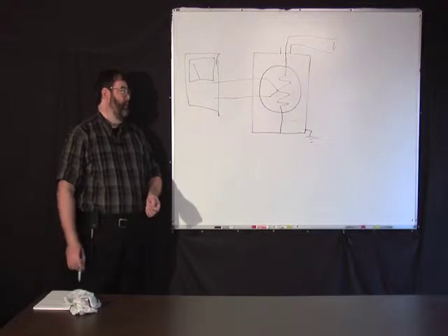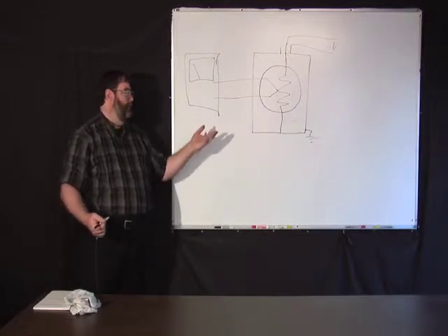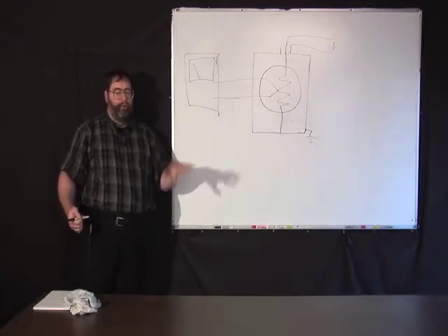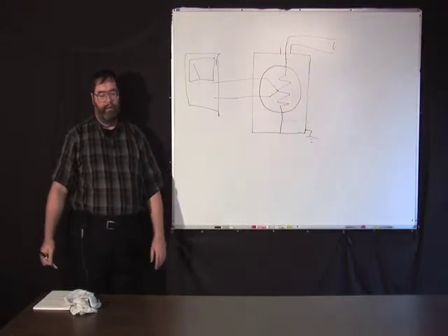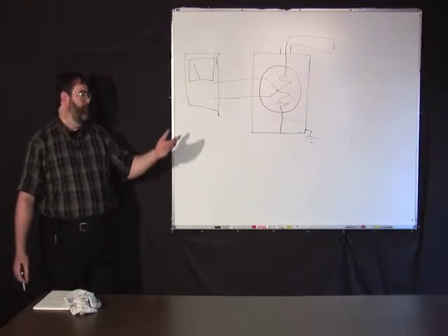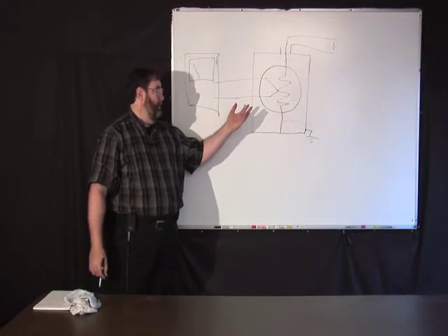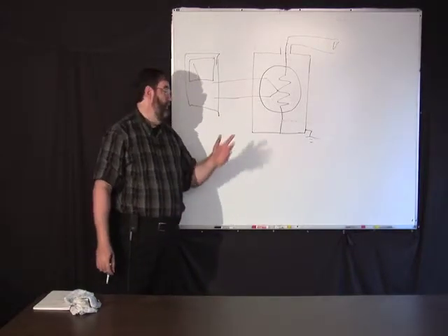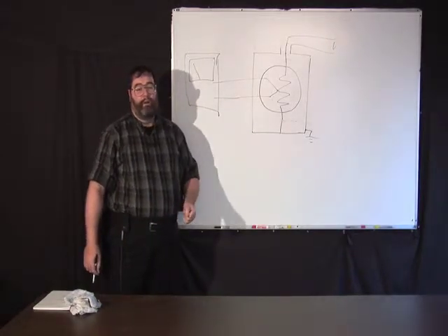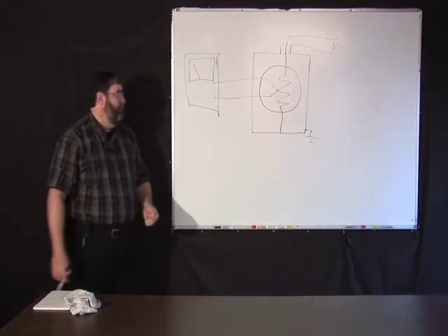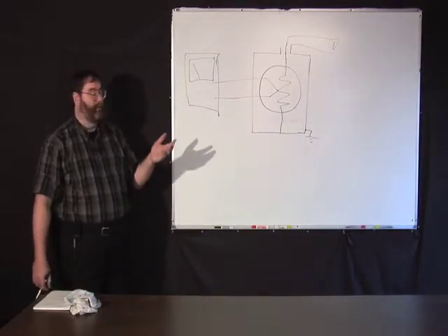DC voltage. Now there's some complications, like you have to measure both polarities of the DC voltage and average them, because there's some effects in here where you could have some differences based on where the thermocouple is actually joined to the resistor, among other effects.